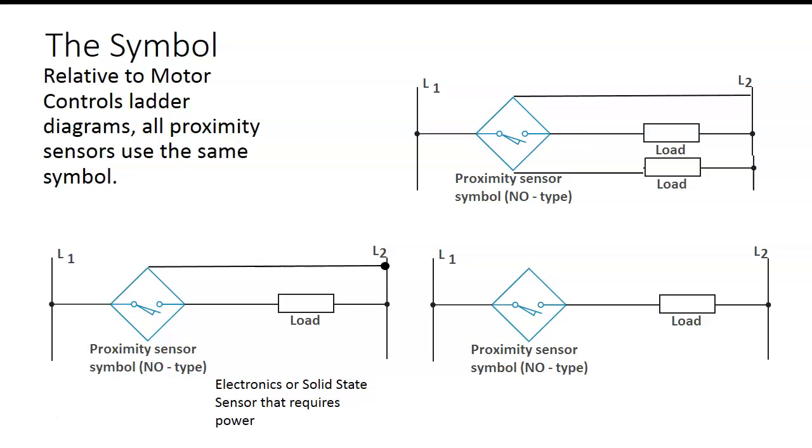And then we have a 4-wire sensor, and this simulates a single pole double throw. We talked about that in class the other day, right? So it's going to simulate one of these. That means we'll have an output that is false when the sensor detects it, and an output that is true when the sensor doesn't detect it. These are called 4-wire sensors. And the standard color code, I'm not going to say you won't run into something different, is that the wire that connects toward L1, positive in DC, is going to be brown.